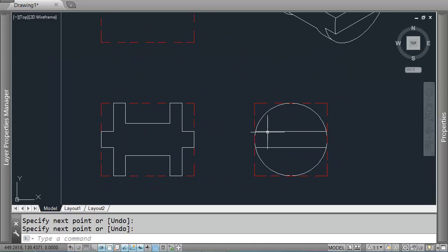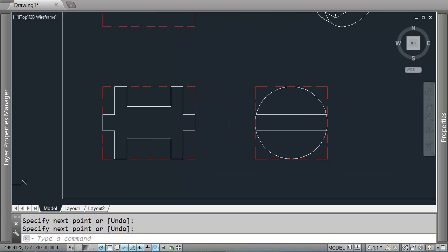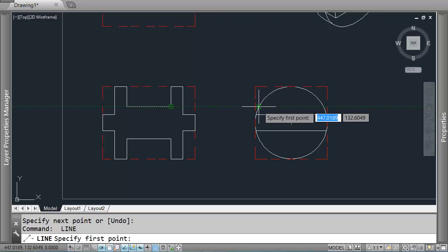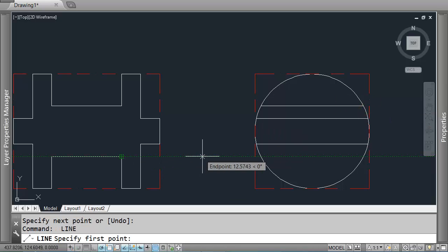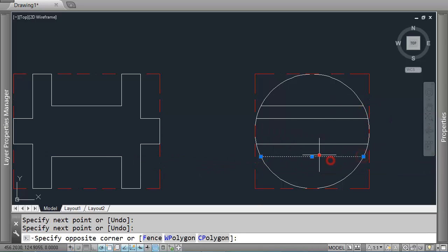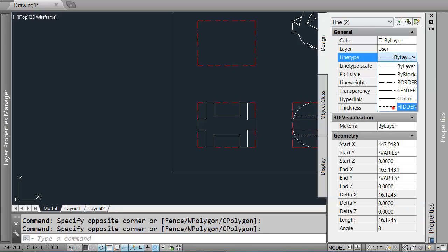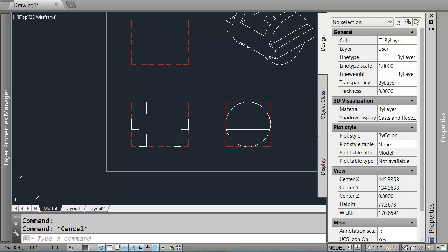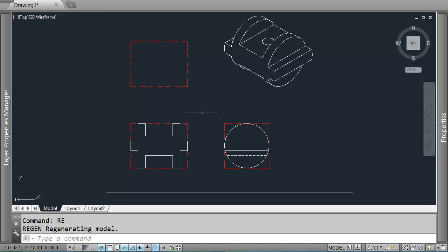Okay, so we have that so far for the outside part of the shape. If we were seeing through the shape to see this inner edge in there, then we would have some hidden lines. So this edge, if I drag that across, it can only start again on the edge of the circle, and we have another one down here. Both of these lines are hidden. We would not see them directly looking on that outer edge, but we would see them as hidden lines in a third angle view. Again, we would have hidden lines for the hole, but I'll wait a little bit for that.